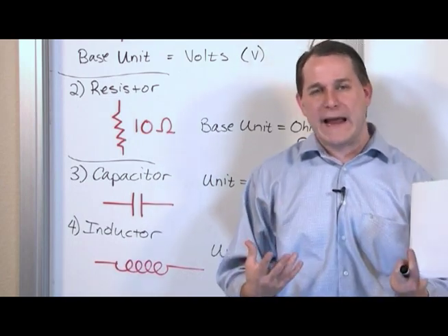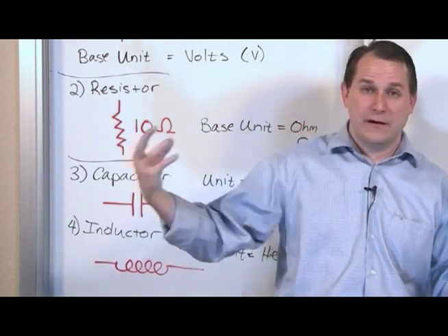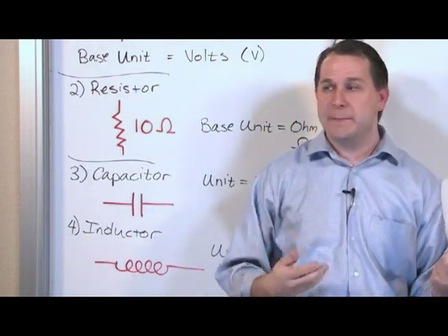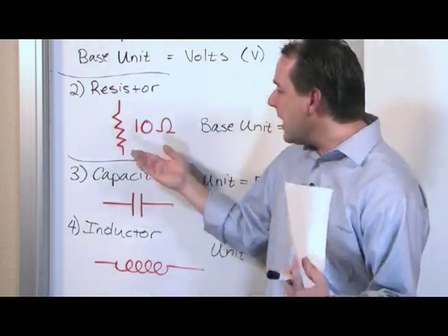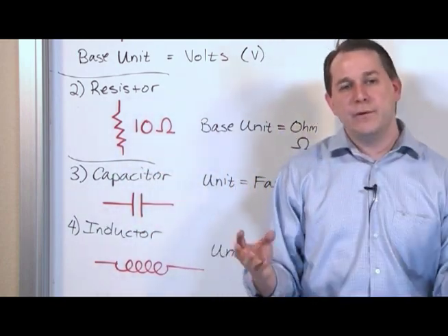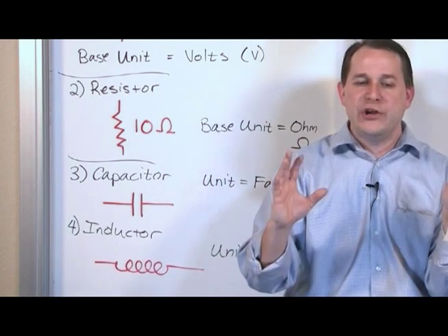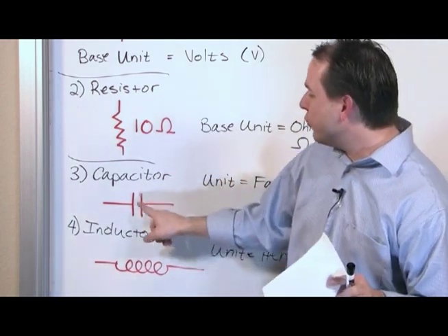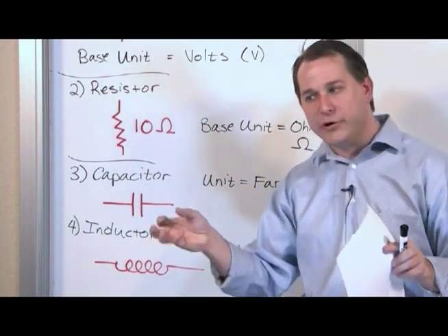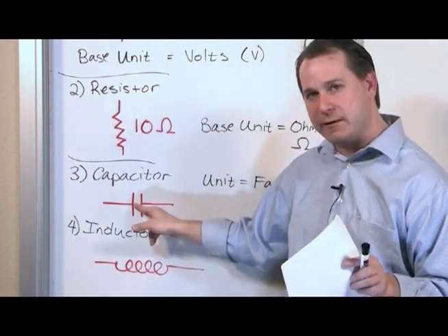You're basically going to have a circuit in there that's going to try to receive signals over the air and play them through a speaker. Well, inside of that radio, you've got capacitors and you've got inductances. And you have chosen those values such that when you turn the knob, usually you're changing the value of the capacitor in the circuit. When you turn the knob on the radio, you're changing the value of this capacitance.